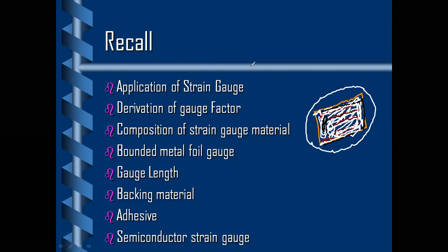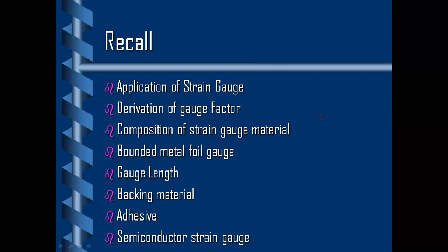This process is carried out to develop a circuit on a copper clad PCB board. A similar aspect is used here: the board or material is a piezoresistive type of material. You generate the circuit, that circuit will have the material on it, and that material will act as a strain gauge. Then the adhesive material that supports it and its bonding, its properties and characteristics we have seen, and the problems that can be caused by the adhesive material or by variation in temperature can also be taken into consideration.